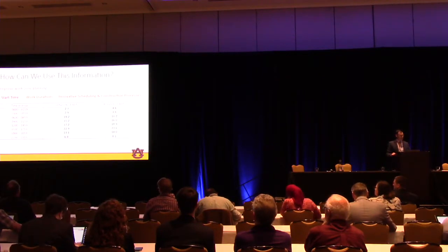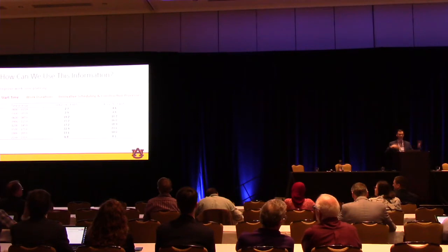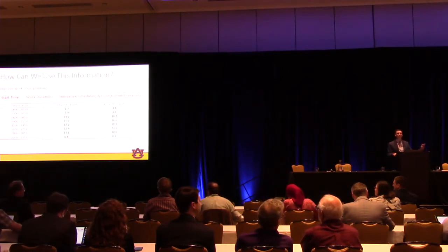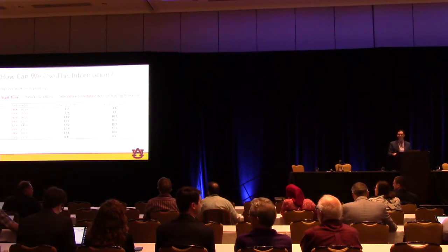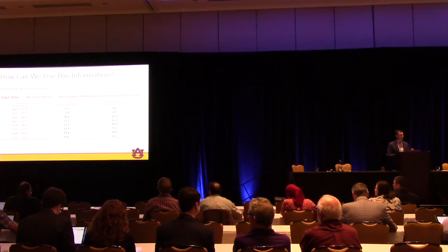These are the percentages of the ADT that's going through a work zone based on the times. They did a huge statewide survey, and you can just see, if you pick a certain start time, the impact that you'll have on the traffic that goes through there. So even at a basic level, we get a sense that how we schedule these things is quite important.